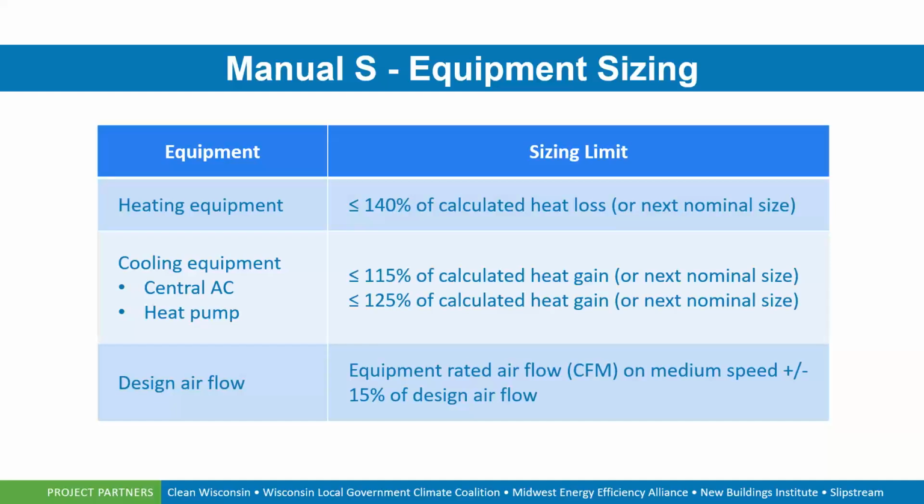Excuse me, because we don't want a fan blower that's producing 1,000 or 1,200 CFM of air when we only need 800 CFM based on the Manual J. With that extra airflow, we're sending additional air, which could compromise the heating or cooling effect at the desired location because we're getting too much air distributed. We're going to lose temperature. We can introduce noise into the system. We have to be concerned with getting that air back, not overpressurizing the system. So we want to make sure that we're within plus or minus 15% of the designed airflow.